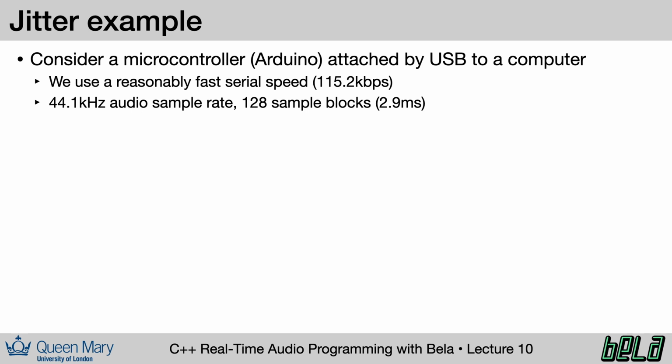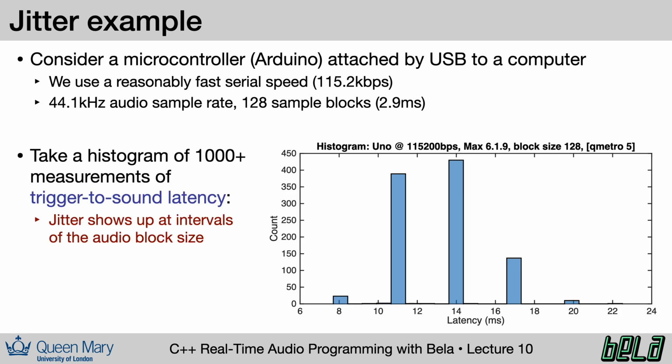Here's a practical real-world example of this. We took an Arduino microcontroller board and we attached it by USB to a computer, which was running Max MSP to generate sound. We had a reasonably fast serial communication and a 44 kHz audio sample rate with a reasonably small block size. And we built a jig which took 1,000 successive measurements of the latency between a trigger and the sound response.